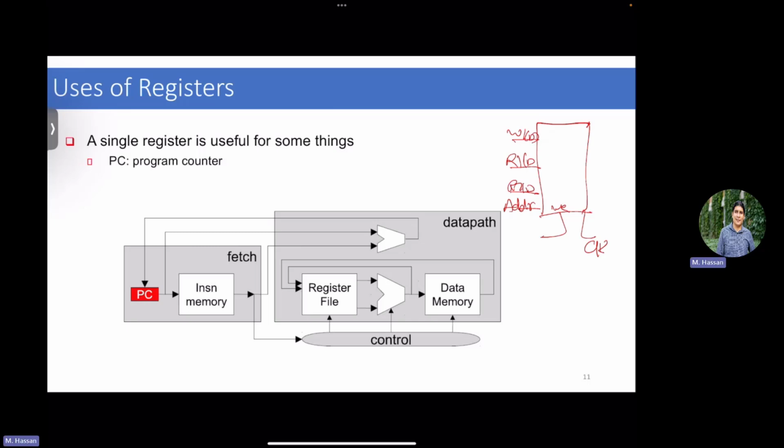So again, last lecture we discussed why we need two read ports and what the trade-off is, right? Most instructions have two read operands, so it will make it faster. Why only one write port? Because at maximum, one instruction would have a single write operand. Then you have the address to read this. Now let's discuss a little bit, given our MIPS ISA, what is the width of every one? First of all, our address: if I have 32 registers, how many bits do I need for the address? This we already said last time, we need 5 bits, right? So you have 5 bits for your address.